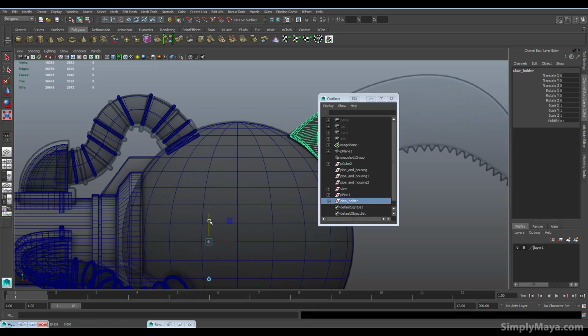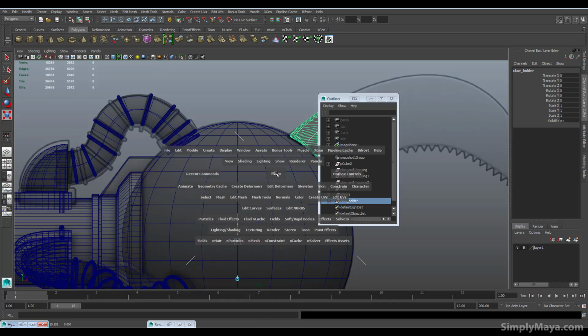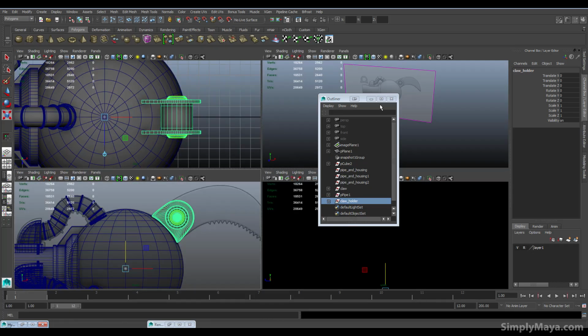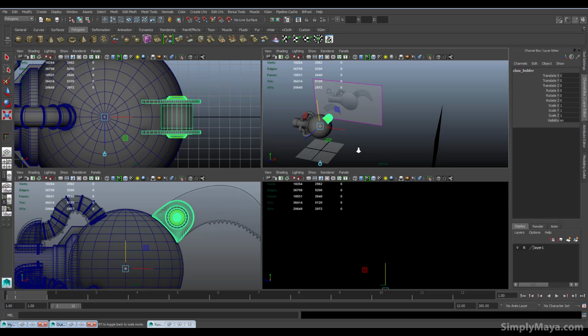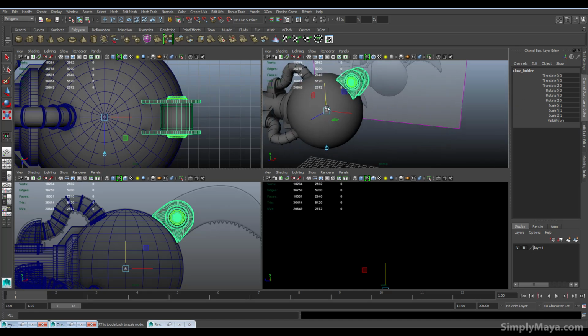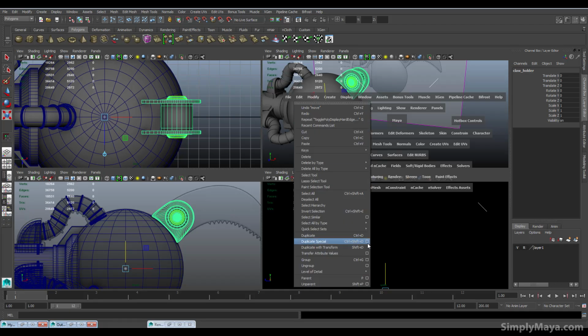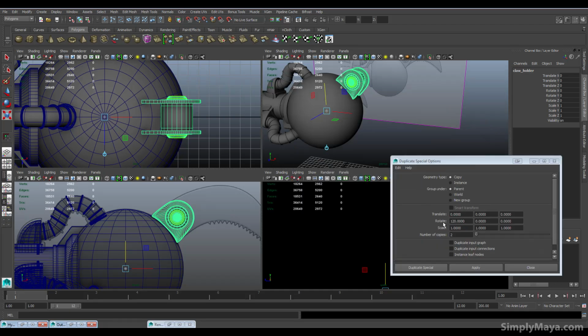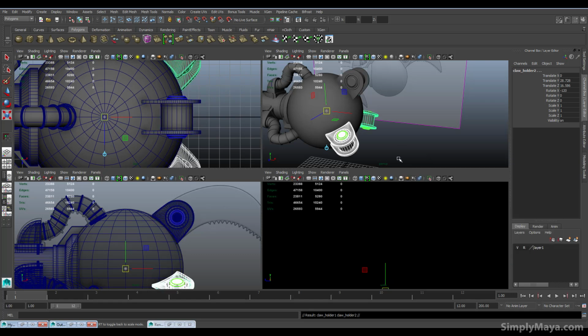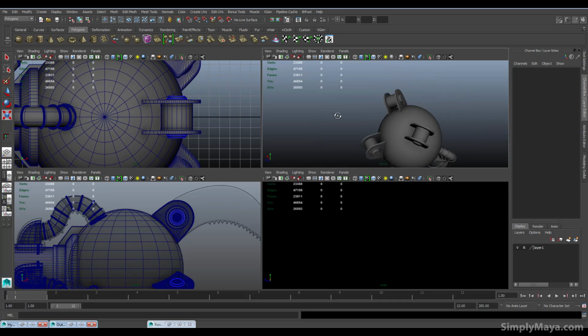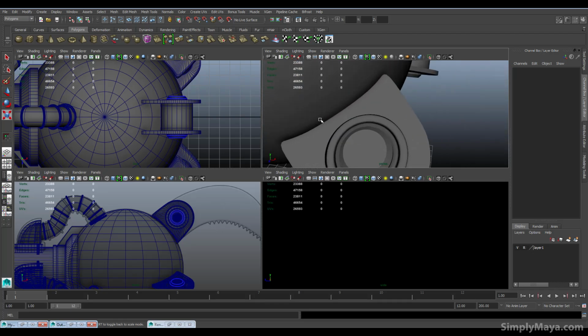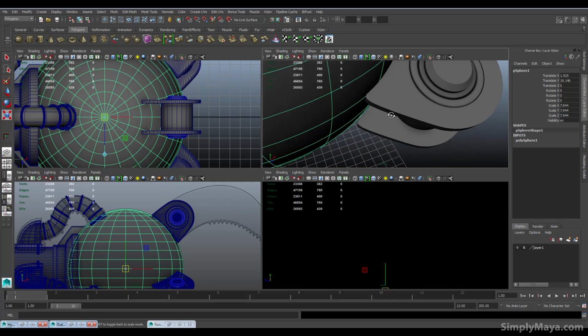So there is our sphere center on that axis, and here it is on this axis. Okay, so I'm going to select everything in this group like so. Its pivot point is here, so I just have to go now, Edit, Duplicate Special. Okay, rotate is 120, scale is 1, number of copies is 2, Duplicate Special, so just put those on for me. Magic. And they're even pretty much in the perfect place.